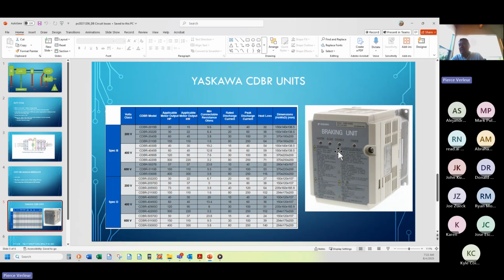And it's a bigger capacity switch. We size them on amps. It's an I equals E over R circuit because it's DC. So it's pretty easy to size how many amps are coming back at you. And if you ever need any help with that, drop me a note. I'll size it for you quickly.